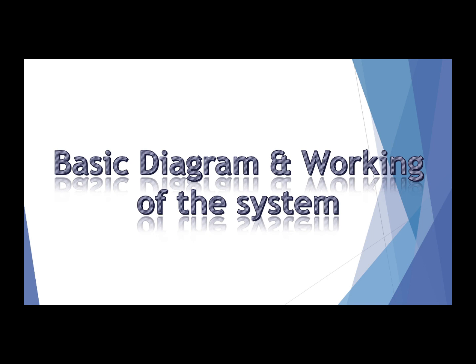Let's introduce how our project works. I have created a basic diagram here through which you can understand what's actually happening inside the total assembly. Our mother component is the Arduino Nano, and assume that we have programmed the Arduino according to our desire. To run the Arduino Nano, we need a battery, but a battery alone is not sufficient. For that, we need the MT3608 boost converter, which will continuously give a supply voltage of around 9 volt to the Arduino Nano.